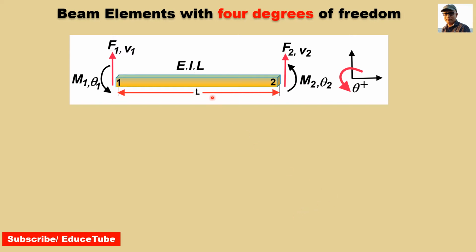But in the case of a rigid jointed plane frame structure, the loading generally consists of axial, shear, and bending forces, and the effect of which must be determined by axial, shear, and bending effects on this element. And once we assume that, we can derive the stiffness matrix for this beam.